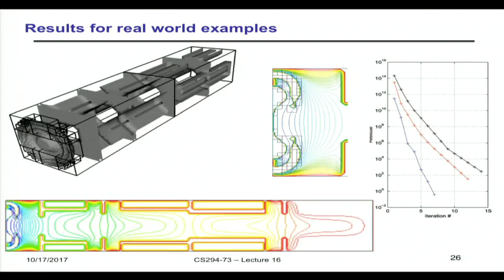Generally, if you see an algorithm settle into that kind of a flat slope, there is a mode in there that your multigrid hierarchy is not directly addressing, or it's the one that's least damped by your multigrid residual. Oftentimes I will take something like that and run those problems through an eigenvalue solver to see what is the primary nature of that mode and how it is not getting damped. And usually I can turn it back into a more steeply descending curve by asking, how do I need to change my parameters or my interpolants to get that better? But that's how complex this gets.